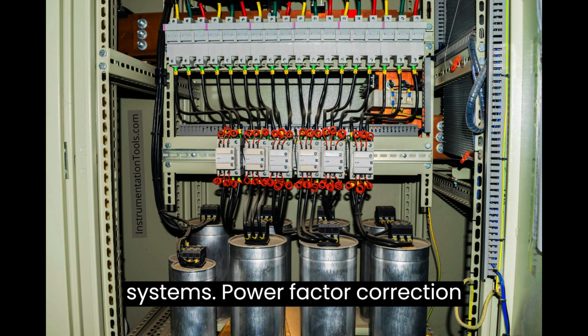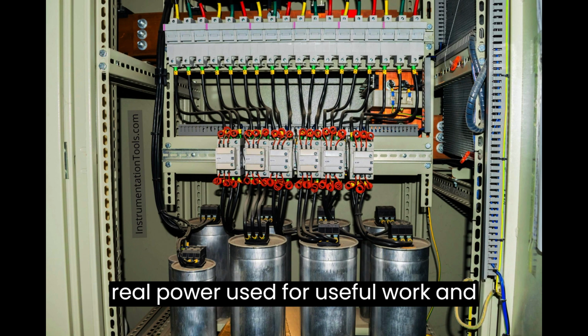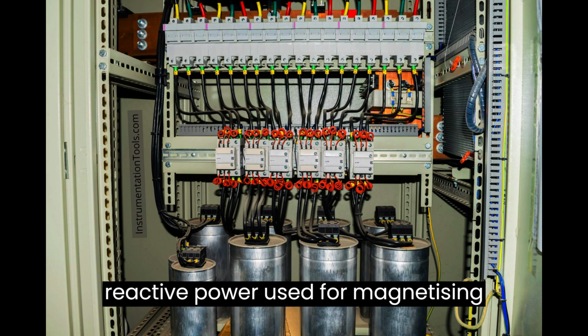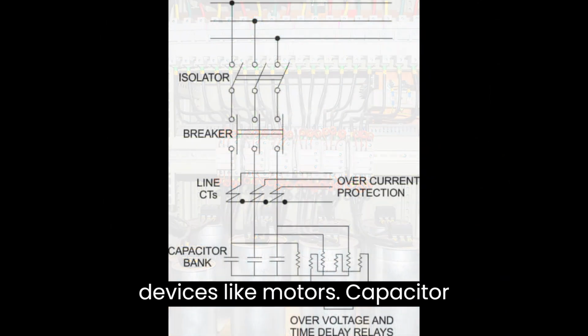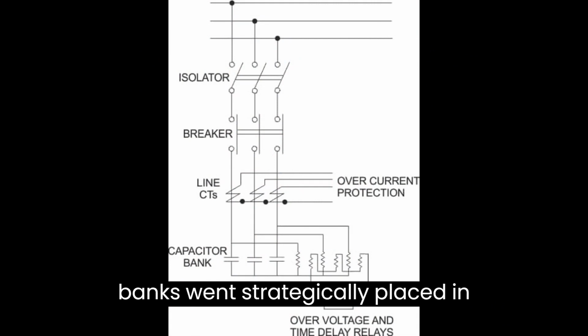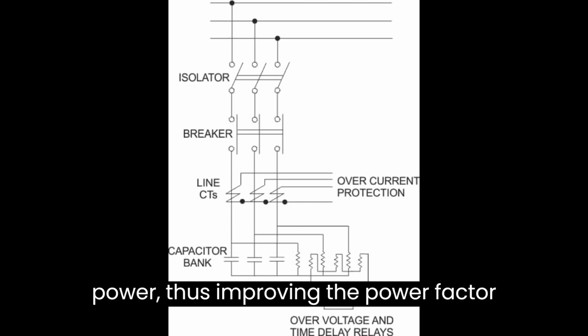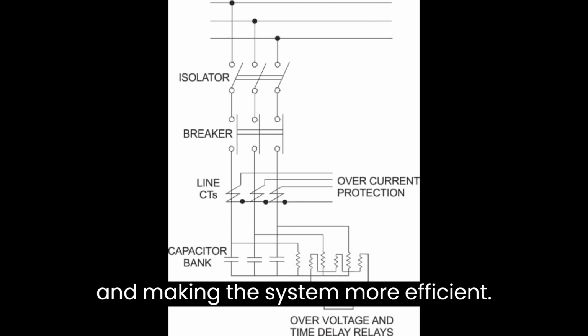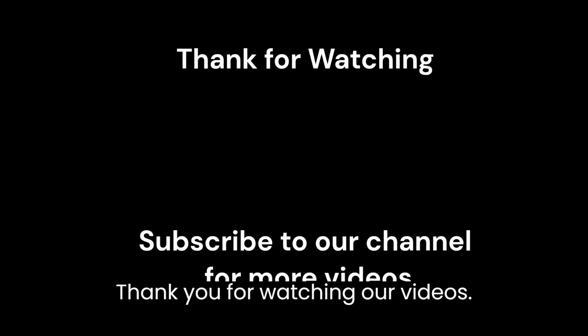Power factor correction involves adjusting the balance between real power used for useful work and reactive power used for magnetizing devices like motors. Capacitor banks, when strategically placed in electrical systems, provide reactive power, thus improving the power factor and making the system more efficient.